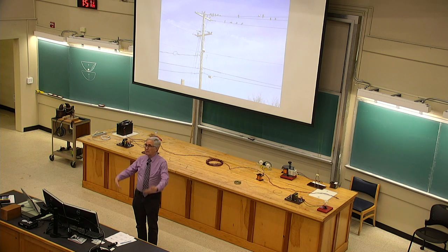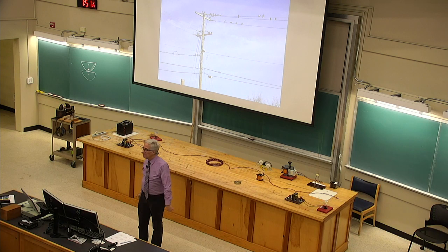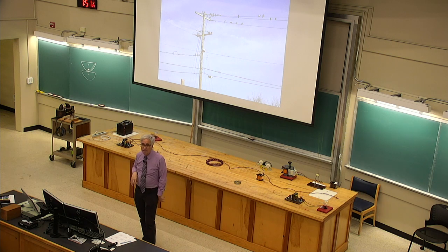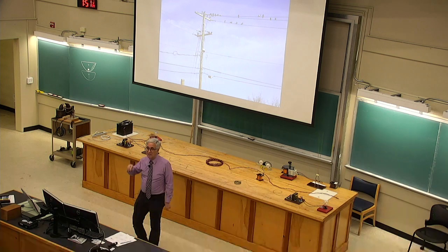So for practical purposes, the one to be concerned about, the big slot and the round hole, you can touch those, don't do it. You can touch those all day. They should be, if wired correctly, they should be safe. It's the hot wire, or load power, the short slot that's dangerous.